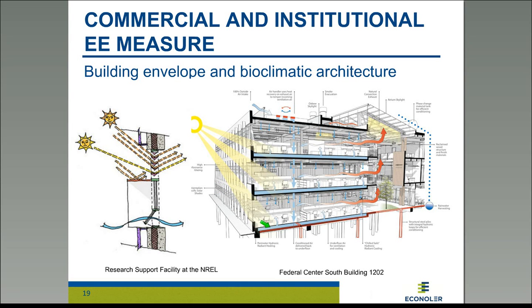So you have also low temperature distribution, hydronic systems. You have a low pressure underfloor air distribution system, so you use natural convection, in fact, to ventilate the building. So it's not the high pressure from ventilators that moves the air mainly. It's the natural convection, so the air picking up warmth and rising gradually and getting out by these louvers here at the top.